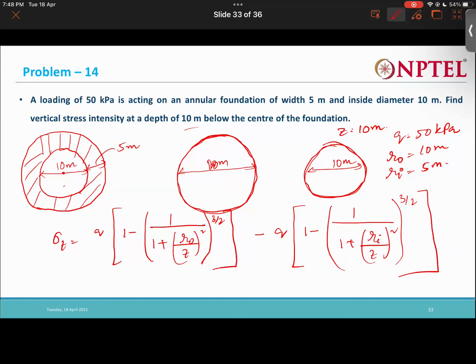Can we use the symmetry and apply the load at the center and find the solution? Like, can we use the symmetry, like point loading? You are saying that we can; we can check this later, how much it is actually coming. It won't be the same, because for a point load the stress is just below it, and see here there is no stress directly below this, right? So when a point load is there, it will come out higher, obviously. It won't be the same.